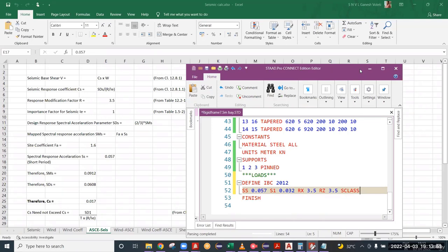So if the soil class of the particular location is not known, we can take soil class 4, nothing but soil class D, that is medium stiff soil. That is not too loose soil, that is not too hard soil. So we have to take on an average soil class 4, soil class D. Soil class 4 in the sense A, B, C, D. D indicates 4. Okay. Soil class 4 indicates soil class D.